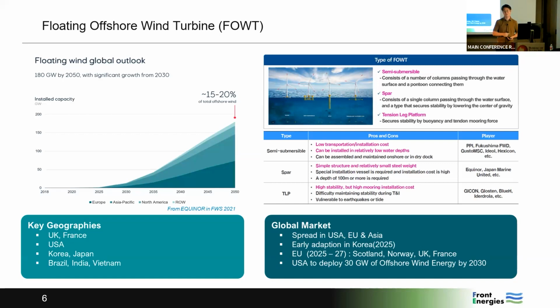So quite a large moment is affecting the floating structure. That's one thing. The second thing is that it keeps rotating to generate power. The rotating structure generates some vibration. This vibration produces fatigue. So that's why the substructure and this floating offshore wind turbine structure suffer a fatigue issue. It's a major concern, so we need to consider those characteristics. And also the three different floaters, semi, spar, and tension leg platform, have different characteristics. According to the excitation or vibration, some floaters have a resonance, some floaters are too big, some floaters are too lengthy.